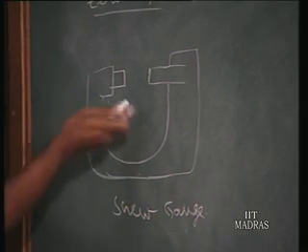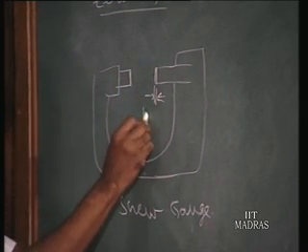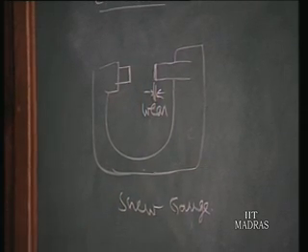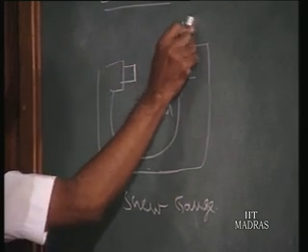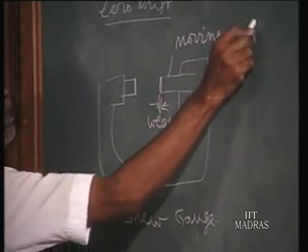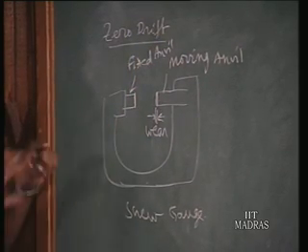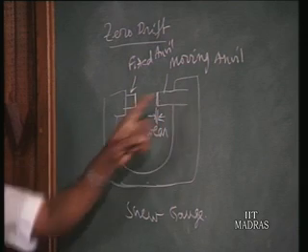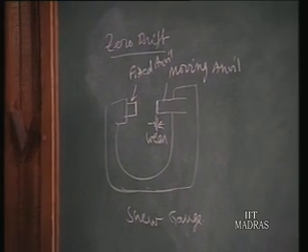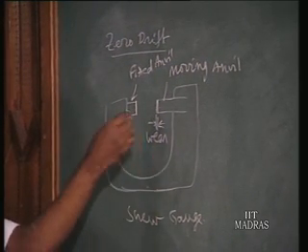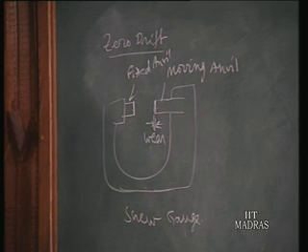Suppose we are using the screw gauge for a number of years, with repeated bringing together, you will find some wear may take place. Due to wear and tear, you find some portion of the anvil has been worn out. So when you bring the moving anvil to touch the fixed anvil, the reading in the instrument should be 0. This is the ideal case, but you will find due to wear and tear, it rotates some more graduations, and then you find there is zero drift in the instrument. When brought to contact, zero is not indicated, so it is below 0.